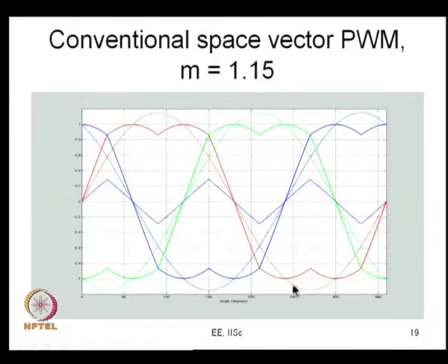And if you go to conventional space vector PWM, the third harmonic component, the triplen frequency component, is, so this is the sinusoidal component. There are 3 phase sine waves, there is a middle valued wave, you take 50% of the middle valued wave, this is your common mode component, which looks roughly like a triangular wave. This looks like a triangular wave because what you are doing here is 50% of the R phase wave, and the R phase wave is going through the zero crossing. Close to the zero crossing a sine wave looks almost like a straight line, so this also looks like a straight line as I mentioned before. Therefore, you add this kind of common mode component, and the resulting modulating signal is what you get here.